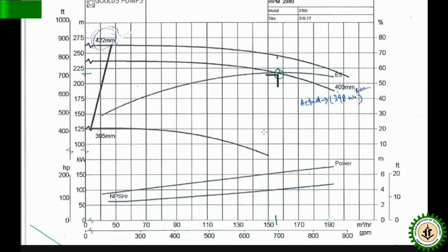Now the point is, you cannot easily vary the speed of a pump. Why? Because you need a variable speed drive. In 90-95% of cases, pumps have no variable speed drive. In some cases, if it is a big kilowatt pump, or power consumption is very high, or you require sudden throughput up and sudden throughput down, flow up, flow down, it is recommended. Cost is also important, because you have to get the payback. If you are investing something, you have to see after how much time you get your money back.